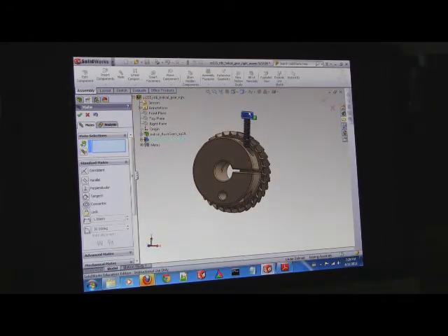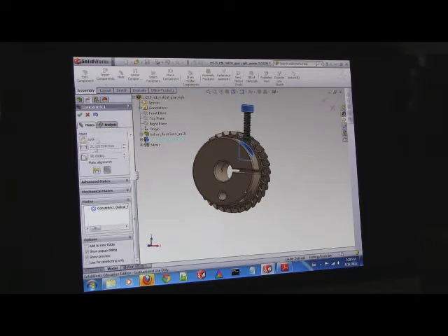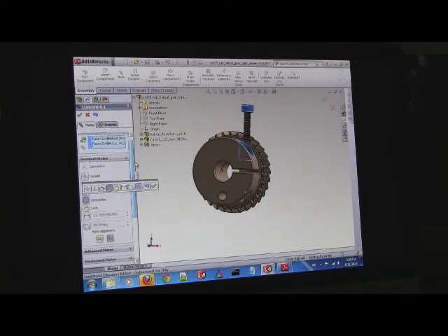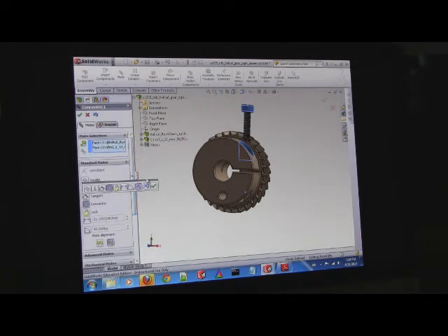Okay, now watch my screen for a sec. See, it's constrained me to be concentric. I can slide along, but that's it. Now, say we screwed this up and it actually looked like this, which happens a lot. Just press this button. This button just toggles the direction of that. So everybody practice that. And this is a concentric mate.